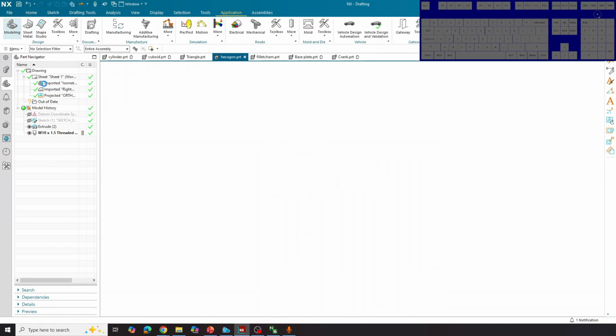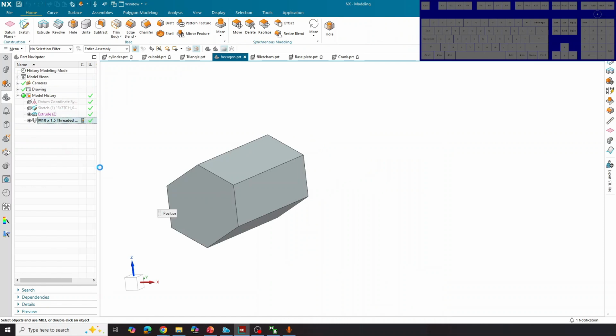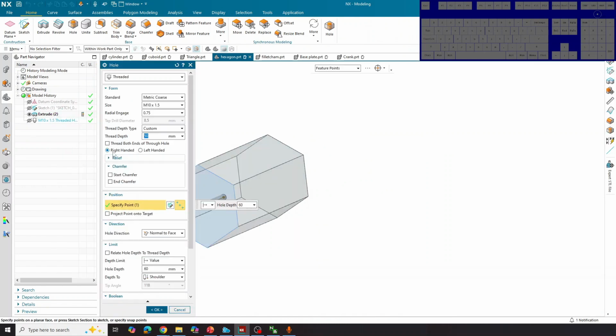You might also see that it specifies over here right-handed or left-handed. And this just means, so right-handed just means that it screws in, so something screws in using a clockwise turning, and left-handed means that it screws in using an anti-clockwise turn, okay? But generally, for most, like 90% of screws made, I believe, off the top of my head, most screws will be right-handed. You can certainly buy stuff that are left-handed as well, but most of the stuff will be right-handed.